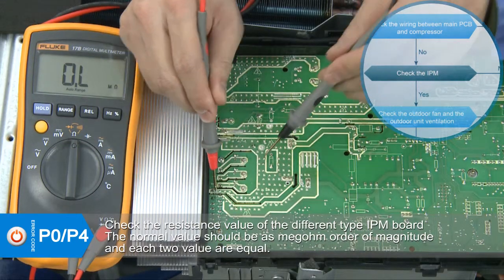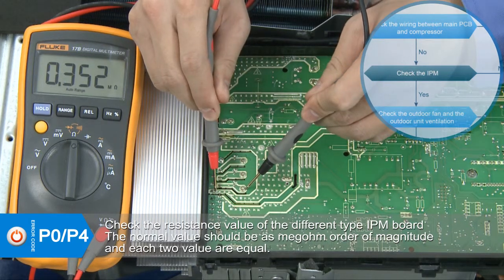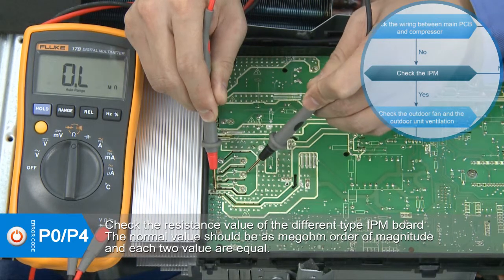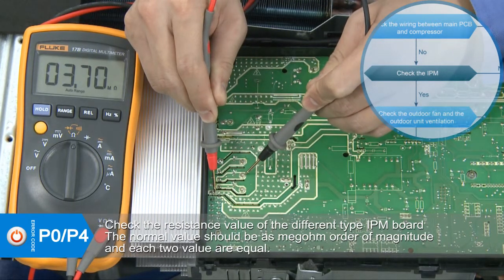Check the resistance between N and U, V, W. The normal value should be of megohm order of magnitude, and each two values are equal.